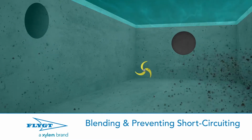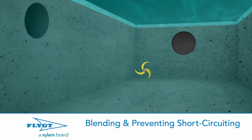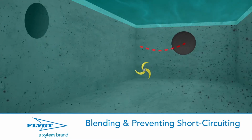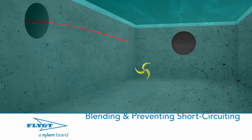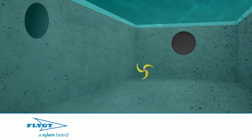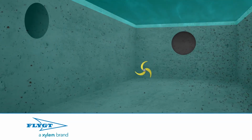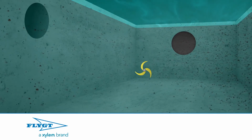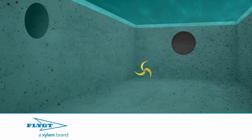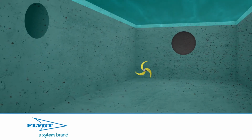Finally, to effectively blend and prevent short-circuiting, we must create a homogeneous mixture, given a continuous inflow and outflow of fluid. Otherwise, the incoming fluid could pass quickly through without mixing thoroughly with the fluid that is already in the tank, or staying long enough to achieve the desired reaction. Whatever your mixing needs, a clear understanding of mixing duties will help you define the intensity of mixing you require. With that information, you can then choose the appropriate tool and settings for the job.